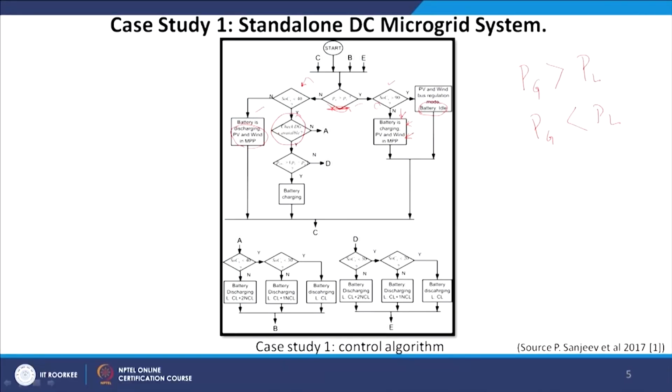So, the third option available to me could be to check the availability of the diesel generator. And if the diesel generator is available to me, then the PDG can meet the difference between load and generation. Whatever the gap between load and generation can be taken out from my diesel generator. Now, if the diesel generator still has excess, then I can allow my battery to charge, and if not, then I will come further to this point.